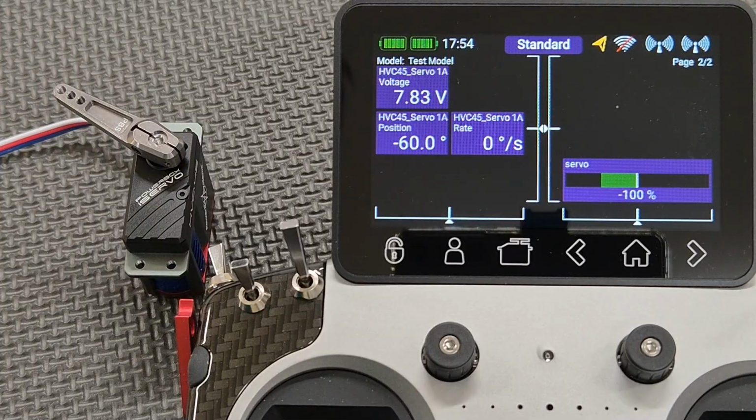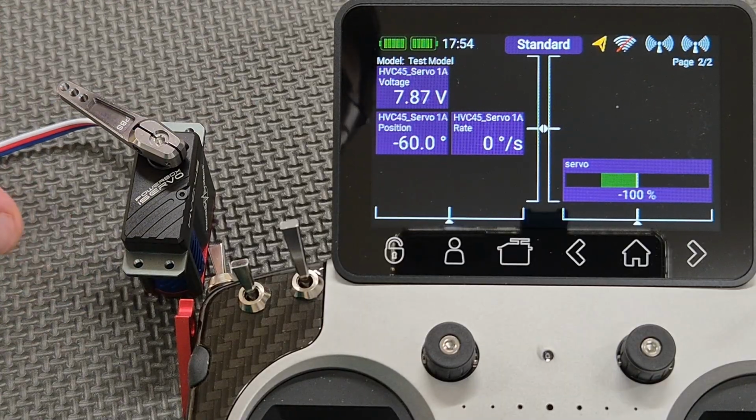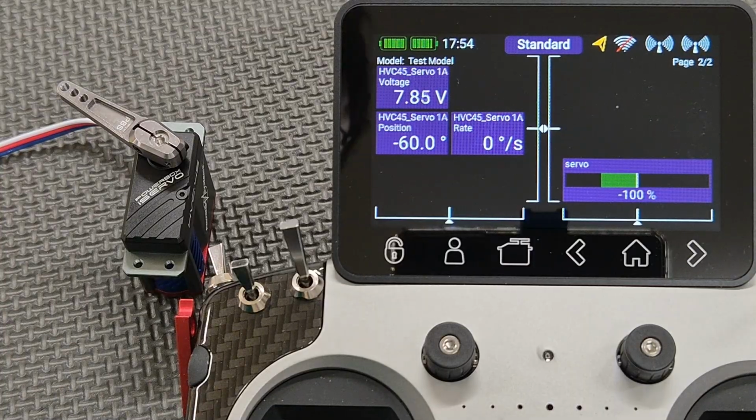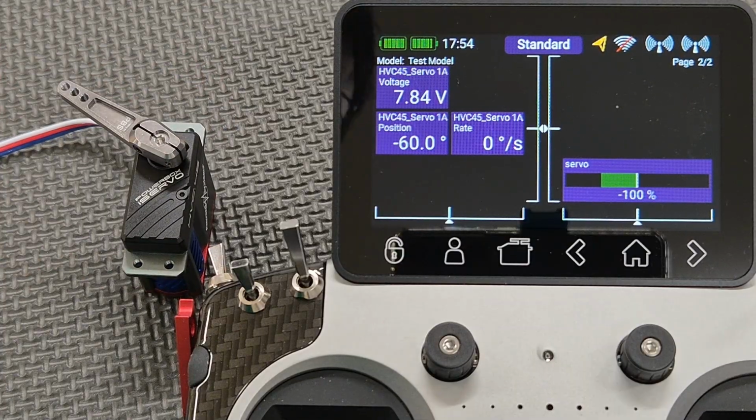So that's an important feature that wasn't available on the previous PowerBox servo, the iServo 5, I think it was. You didn't have the ability to save failsafe in the servo, whereas now with these new servos, you can set failsafe in the servos. I was specifically asked that question in an earlier video. And yeah, it does work, it works well, so no problem there. That's a real handy feature if you're using a P2 bus configuration.